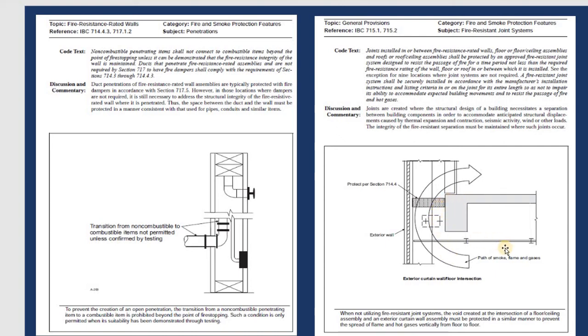And in this one, you can see the path the smoke can take, this way. So during the travel, the smoke can go this way, and any material around it needs to be protected for that section. The exterior wall already has fire ratings, but the smoke can travel out through the system, from the ceiling out to the roof. If you have some material there, you need to qualify it for protection from the smoke.